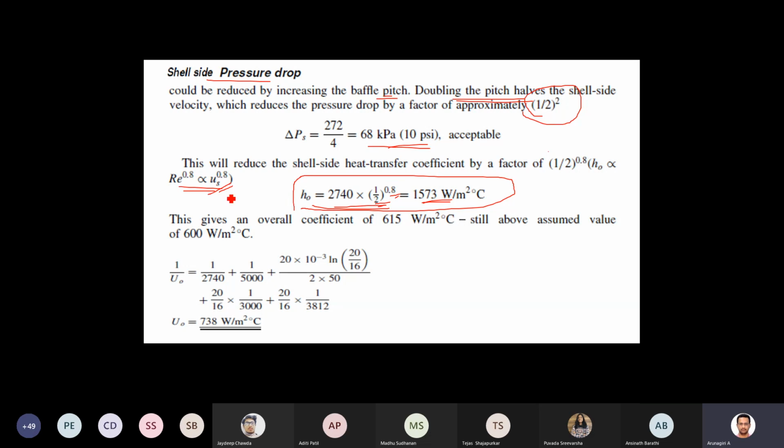Okay, this is approximately, or you can do by procedure also, because you can check what is the change in JH, because your Reynolds number will also change, no. So if you change the velocity, what happened? dV rho by mu, no. So your Reynolds number becomes double. If Reynolds number becomes double, you have to see the corresponding JH. That also matters. Okay, this is on approximation.